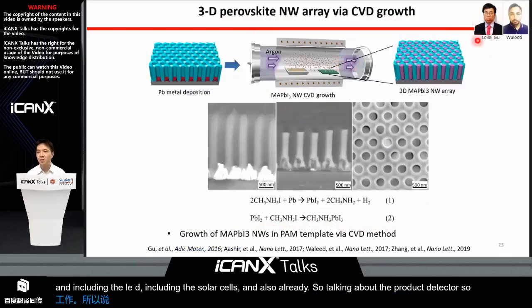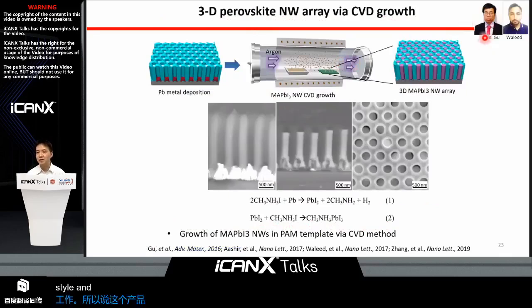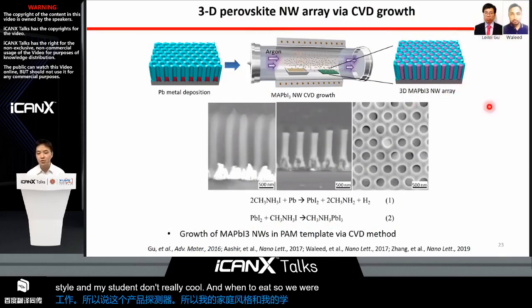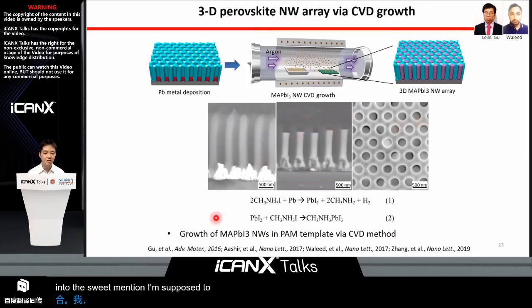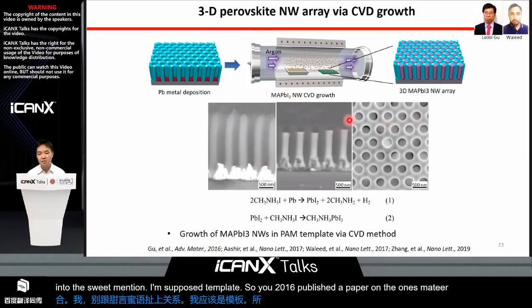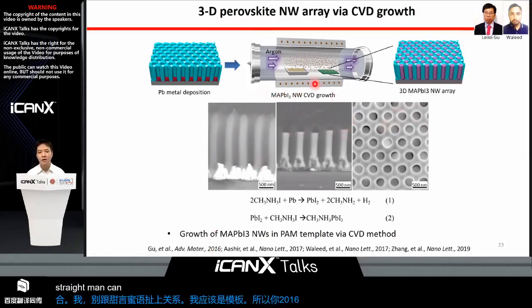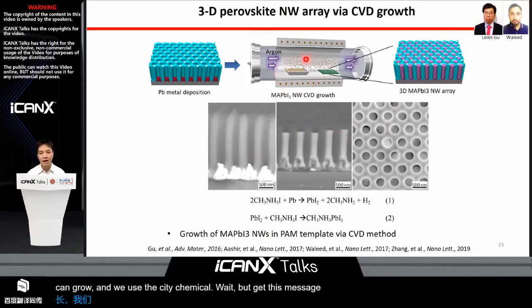my postdoc and my student, Dr. Lei Gu and Walid, worked on integration of perovskite nanowires into this three-dimensional porous template. In 2016, they published a paper in Advanced Materials demonstrating that they can grow perovskite nanowires into the array of holes. We use the CVD, chemical vapor deposition method.